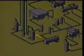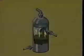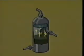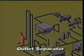Incoming sour gas flows through the inlet separator, where solids and free liquids are removed from the gas. Most of the liquids are separated out by baffles. Near the gas outlet, a mist extractor, sometimes called a mist eliminator, traps liquids entrained in the gas before it leaves the vessel. Some sweetening units also use an outlet separator to remove entrained liquids before the gas goes on to further processing, such as glycol dehydration, or before the gas is sold.